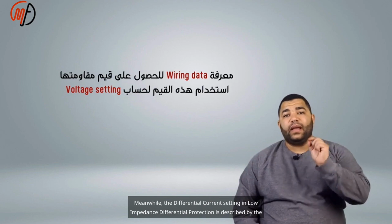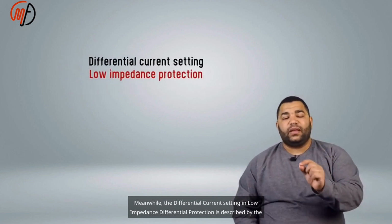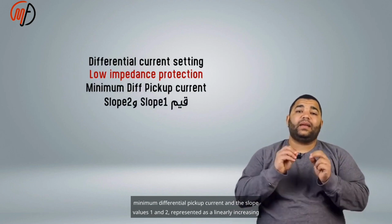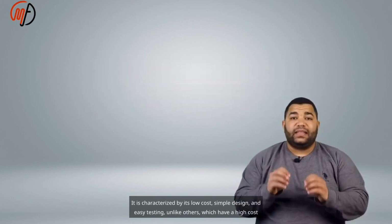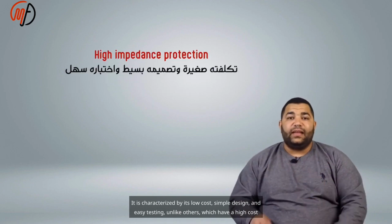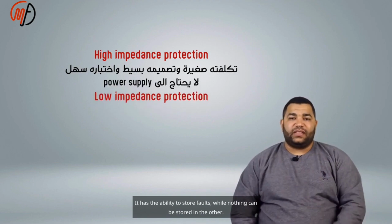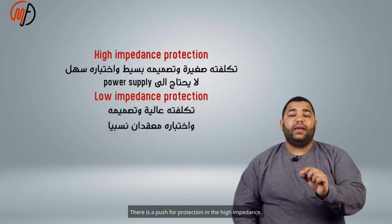and use these values in calculating the voltage setting. Meanwhile, the differential current setting in low impedance differential protection is described by the minimum differential pickup current and the slope values 1 and 2, represented as a linearly increasing coupling, in addition to the value of the unrestrained current. It is characterized by its low cost, simple design, and easy testing, unlike the other, which has a high cost and a relatively complex design and testing process. It has the ability to store faults, while nothing can be stored in the other.